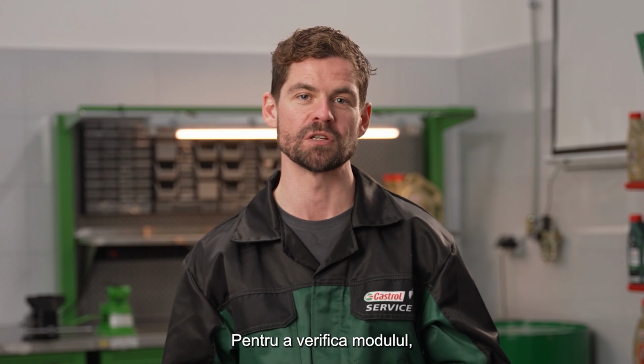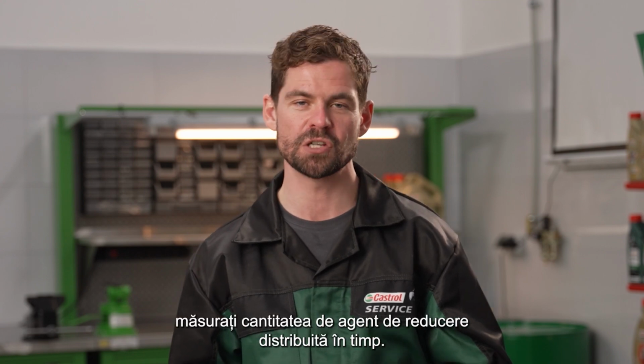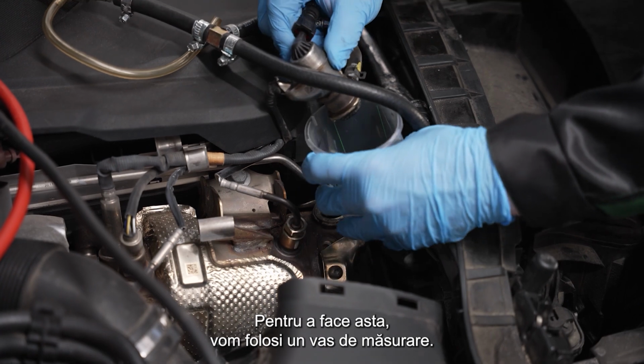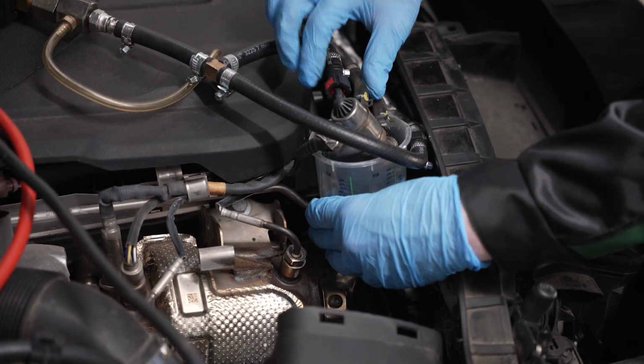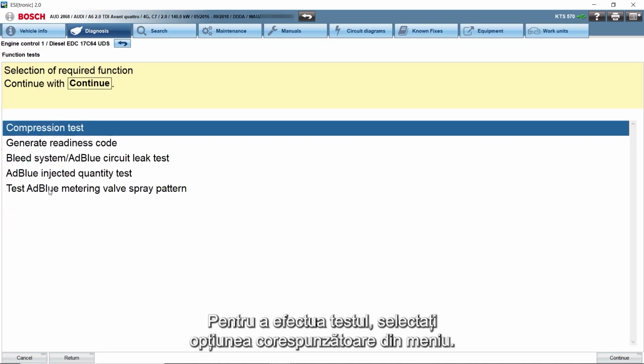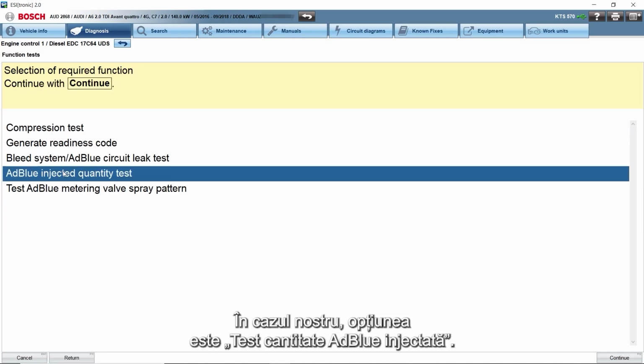To check the dosing module, measure the amount of reducing agent dispensed over time. To do this, we will use a measuring vessel. To perform the diagnostic test, select the appropriate option in the menu. In our case, this option is AdBlue Injected Quantity Test.